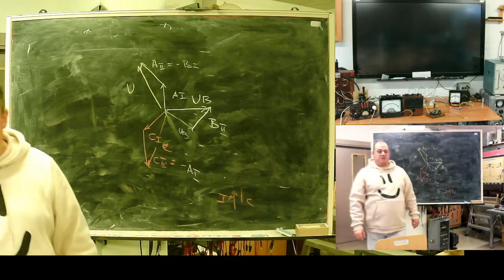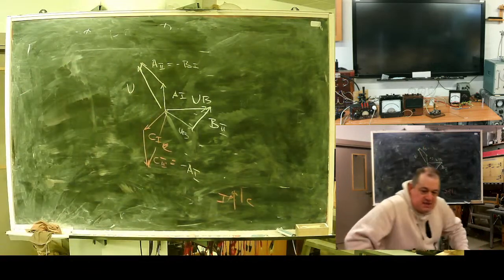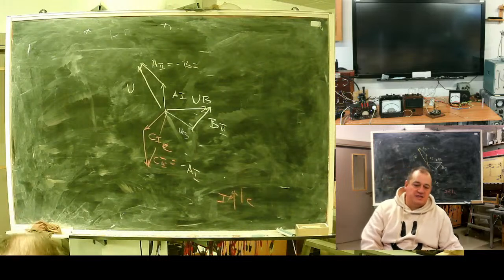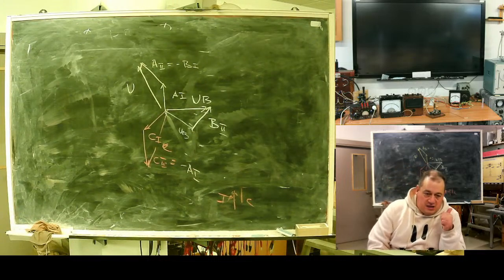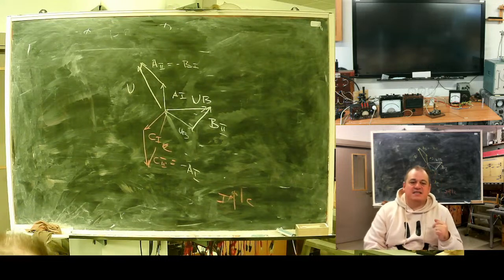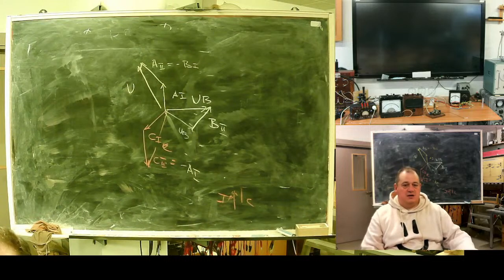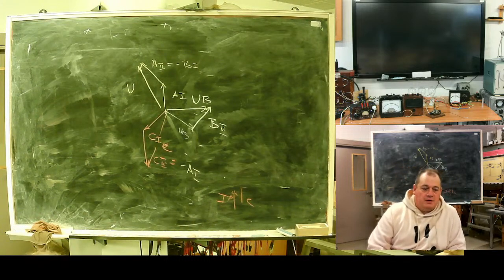So it's a special kind of transformer for networks with high asymmetry of load, where phases are very different. In case of direct sequence, you will see something like this. But in case of zero sequence, this transformer presents nearly zero resistance, very small active resistance. Yeah, special kind of transformer. What else?